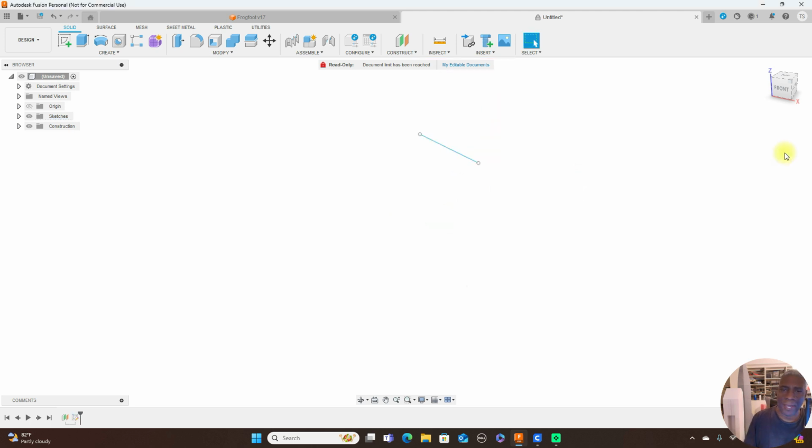And pretty much, that's all you need to know to model thousands of airplanes in Fusion 360. Just those three things: the origin, so you can create a sketch or a form on the origin, or you can insert an offset plane from one of these planes, or from this plane here too.